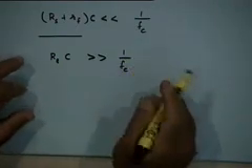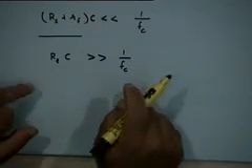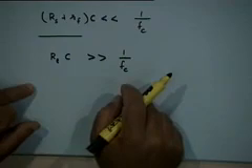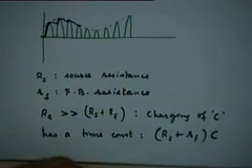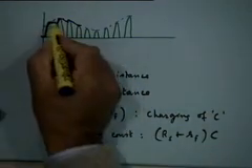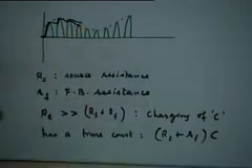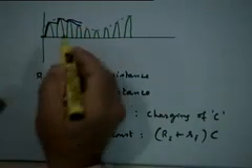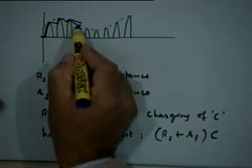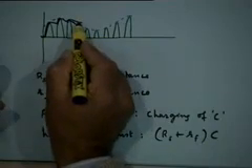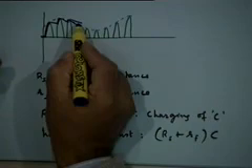But this is one aspect. This can lead to a situation which is not desirable. Do you appreciate that? Let's look at this picture once again. Suppose your discharge time constant is very slow. Let me take a different color now. It can happen that the discharging is very slow. Suppose it is so slow that the next peak comes at a lower value than the amount to which the previous peak has discharged, right?